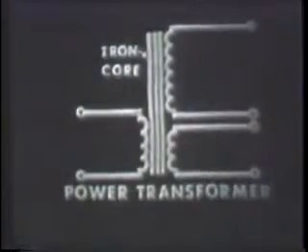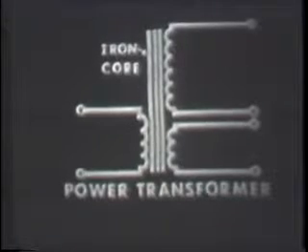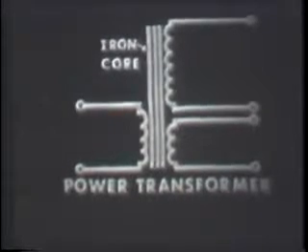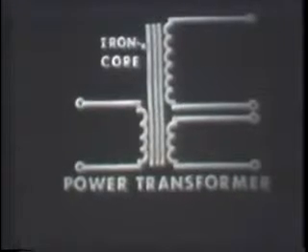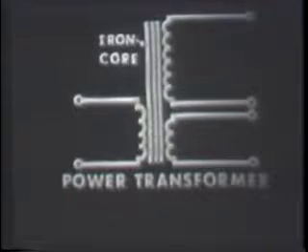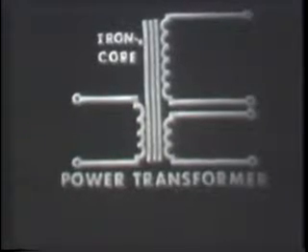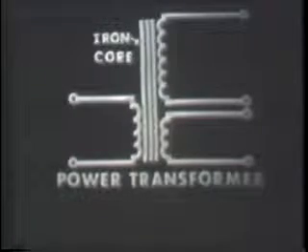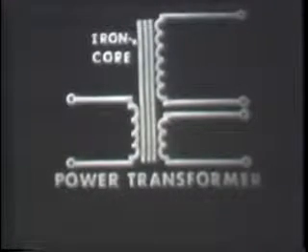Now, quite frequently, and especially when dealing with schematics, you'll have to recognize a type of transformer by its schematic symbol. The schematic symbol for the power transformer can usually be identified by there being more than one secondary winding. In this case, there are two secondaries. However, other power transformers may have a different number. You'll notice that each secondary has a different number of turns.